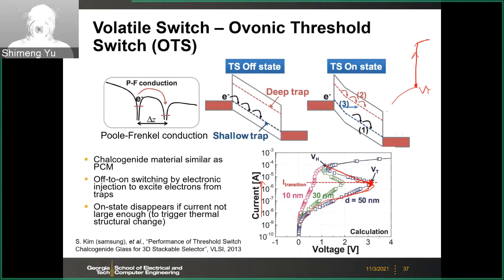So if you drive the voltage, this is how you look at the current. It's something like this. If you do the switching, I and V, log scale. But if you drive the current, because current will be continuous, then you will see this S-shape behavior. If you drive the current, that means from the equipment, your current is continuous. Then you will see the continuous current, but you will see a snapback of the voltage when you sense the voltage.